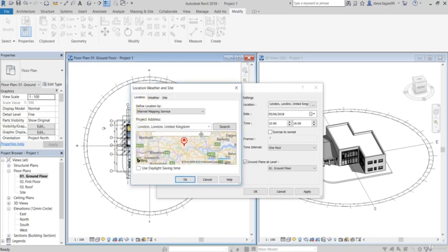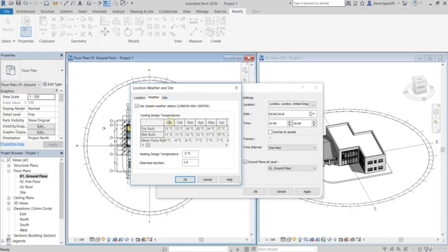When you enter in the project address and give a specified location, the longitude and latitude coordinates of the selected location are compared to an external database, and the closest World Meteorological Organization weather station is selected, and this is where the data is generated from.